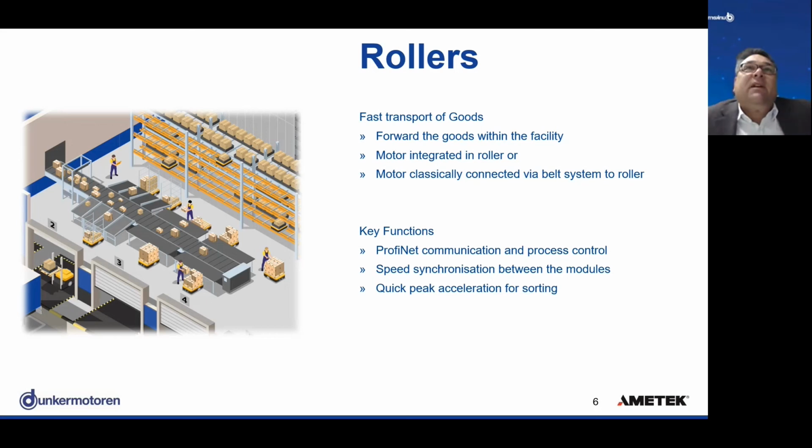So therefore, speed control via the net, the field net communication is also essential here. Also, quick acceleration is needed, because due to the speed of the parcels, the acceleration must be done within some milliseconds in order to feed out the parcel in the right way.